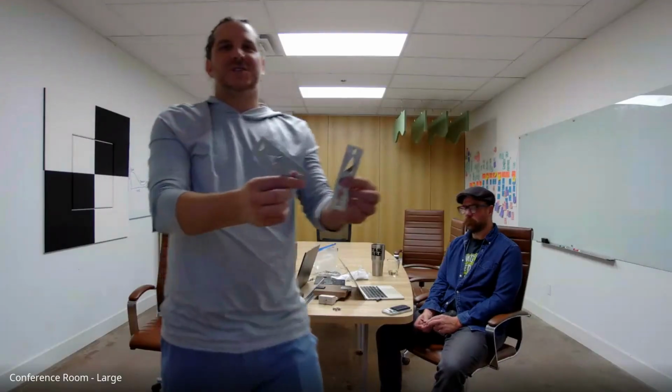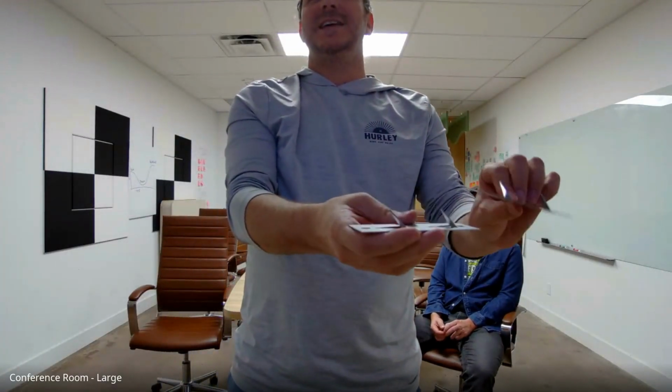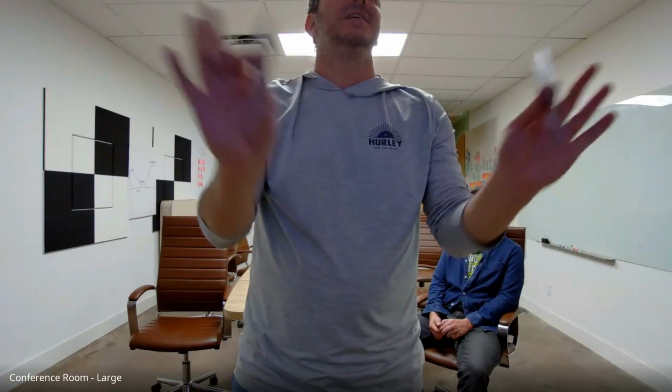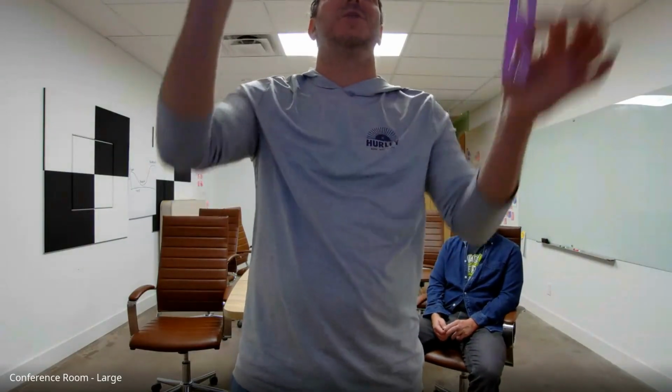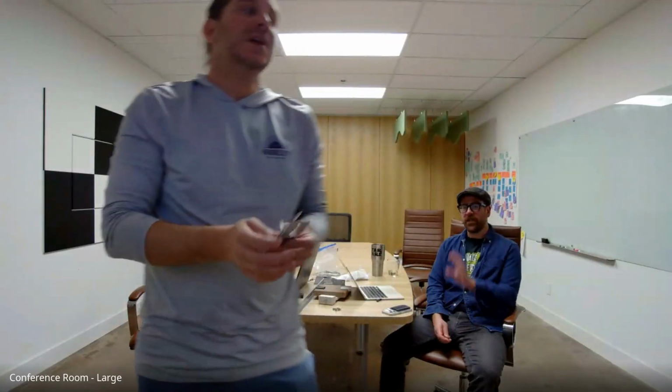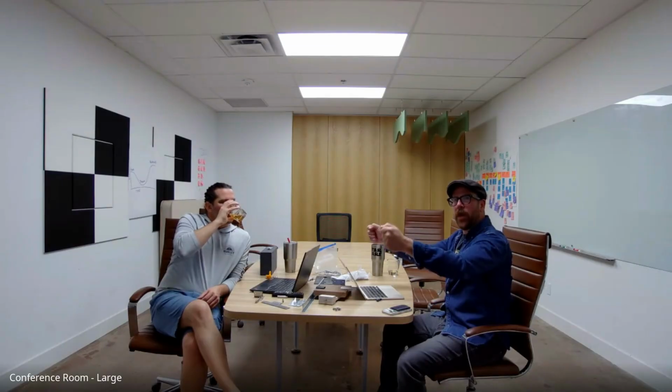This is an impaling clip. They're just spiky little guys here, right? They just get screwed onto the wall and the back of the panel slides right on. Super simple, super easy. They don't need to be exactly placed here. You can just throw them up, pop them on, right? The difficult thing with those is aligning panels though that are close together. No reveals. When you take that panel and you stick it on the wall, you go forward and down to get it on that spike. And so once it's on the wall, it's very hard to put a bunch of weight on or lift it up and get it perfectly level.